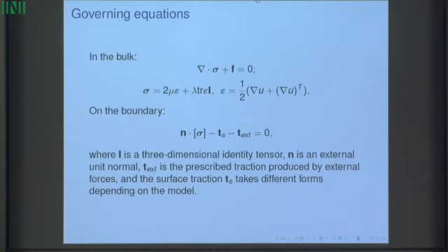If you look at this, this is just a surface traction, the normal times the jump in your stress tensor for the surface. This is just exterior forces applied to a surface. Again, that is classical. And then you get this T_S component, and the T_S component is exactly what comes from your additional surface energy.